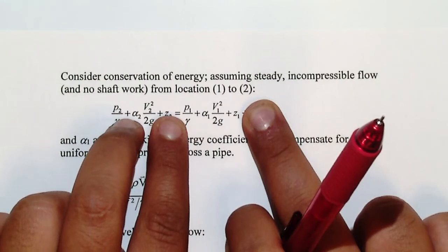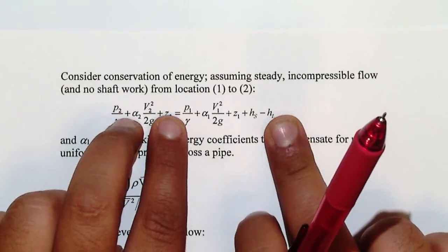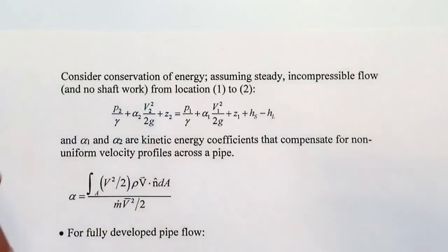So it's not going to be true, except that you have another term, which is the loss inside the pipe. What does it mean? It means that you have a higher pressure and you are coming to a lower pressure, but you compensate for this difference by the amount of loss that you have inside the pipe because of the friction forces. The friction forces are the viscous effect between the layers, and also between the layers and the wall of the pipe.